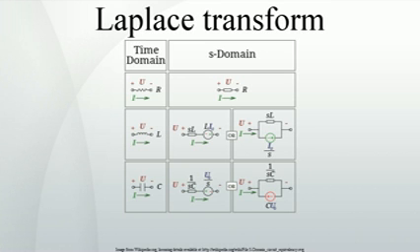Example 2. Deriving the complex impedance for a capacitor. In the theory of electrical circuits, the current flow in a capacitor is proportional to the capacitance and rate of change in the electrical potential, in SI units. Symbolically, this is expressed by the differential equation, where C is the capacitance, in farads, of the capacitor, I equals I(t) is the electric current, in amperes, through the capacitor as a function of time, and V equals V(t) is the voltage, in volts, across the terminals of the capacitor, also as a function of time.